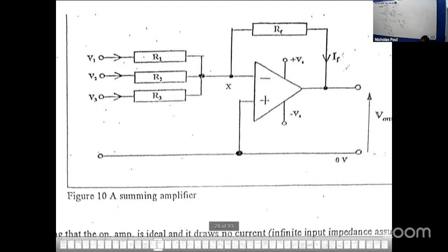Quick question, Jacob, because I have you paying attention there. What type of op amp is this, Jacob? Inverting or non-inverting? Very good, because the positive is connected to earth. Right? Inverting op amp. So this is a special type of op amp. Here's how it's different. You all recognize that the inputs are 1, 2, 3. So this amplifier can handle 3 inputs. Like for those who are into music, the amplifiers can handle a microphone and different things. So here's an example of taking 3 inputs and again 1 amplified output.